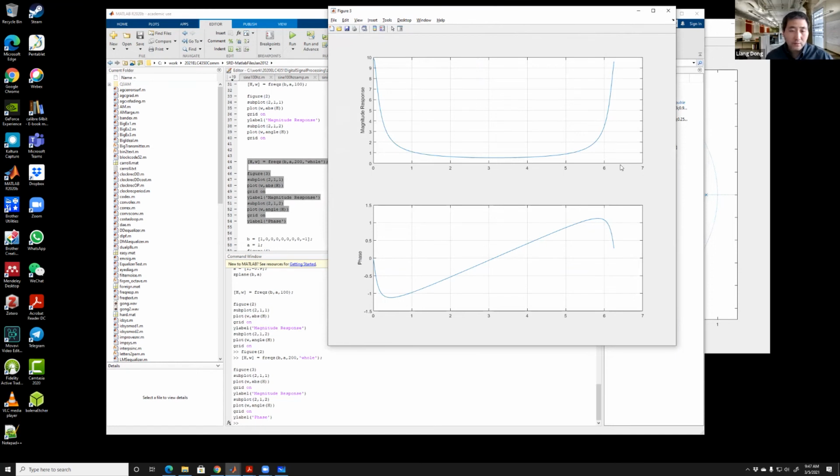All right, but we know we don't really need that, because beyond the Nyquist rate, everything is a mirror image of itself. So you have redundant information. That's why in our original layout, we don't need the whole thing. We can just plot from 0 to pi. That's good enough. In other words, when you travel along the unit circle, you just go half circle from 0 to pi, and you get all the information that should be there. And the same thing here for the phase term on the bottom picture. The phase is also a mirror with the center at pi, or fs over 2.